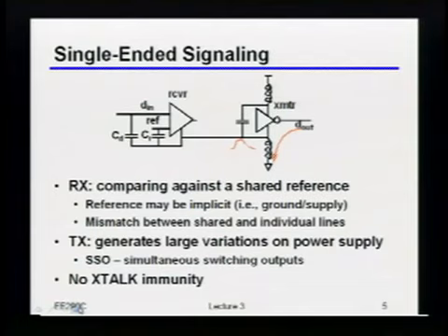So the real issue that you get into when you're talking about single-ended signaling: before, I just drew the receiver as an inverter, but I could indeed try to build some sort of differential amplifier as my receiver. Okay? The problem there is that if you're talking about single-ended, what you're implying is that whatever you're using to set the reference for that differential amplifier is somehow shared, right? It's being used in multiple different links. Okay?